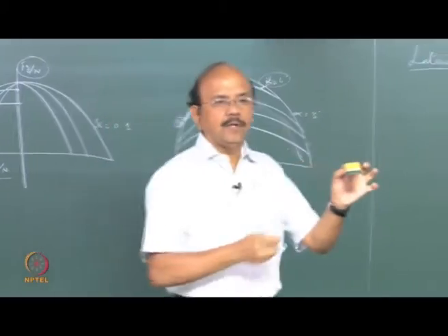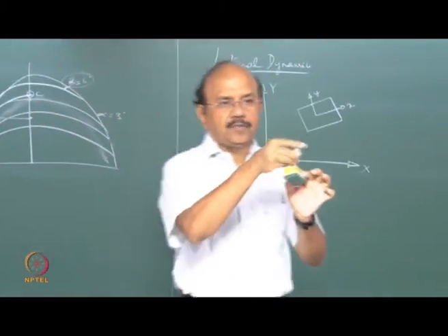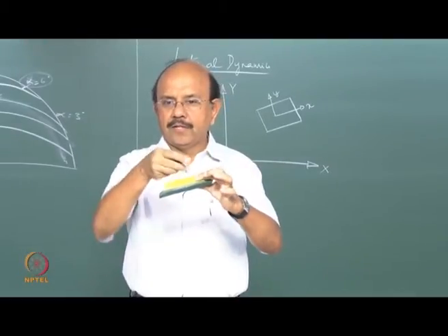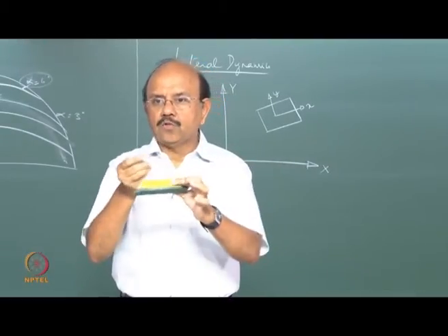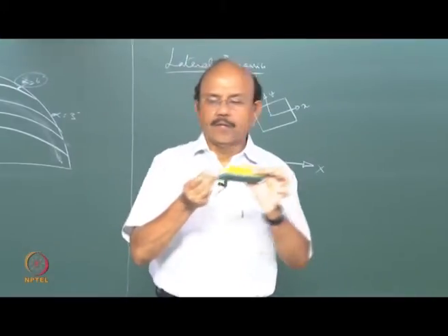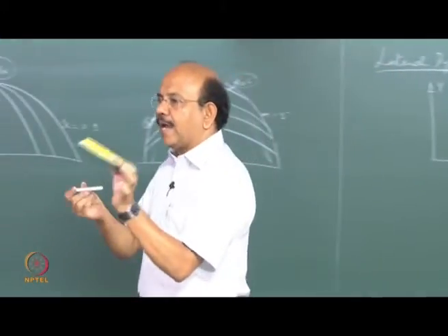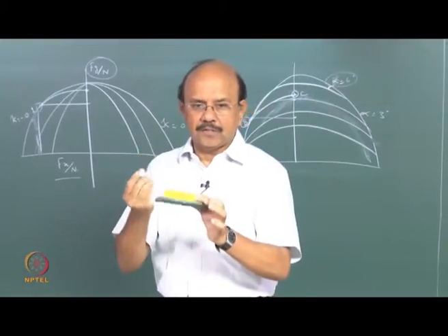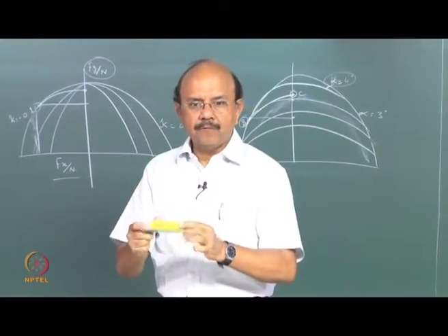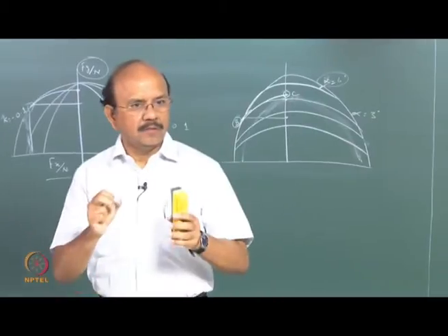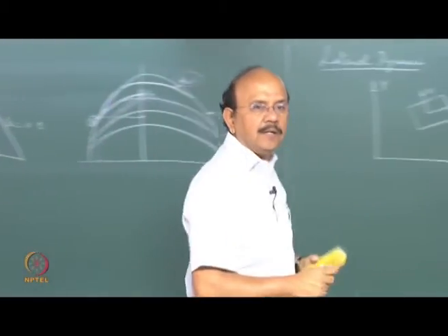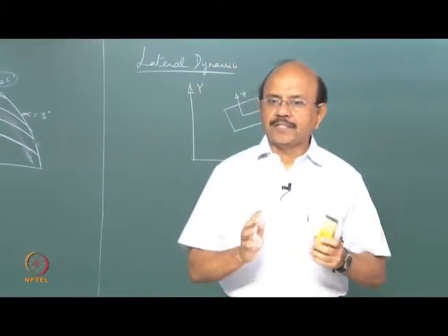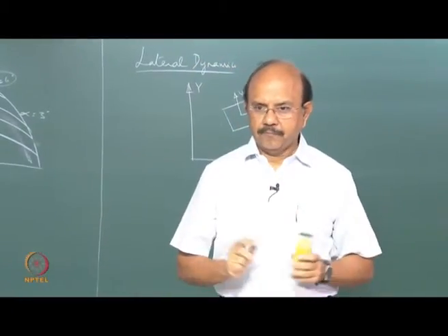Suppose this is the vehicle. So I have a body-centered coordinate in this vehicle. So the vehicle takes a turn, the body-centered coordinate also takes a turn. Okay? So they also move along with the vehicle. In other words, I have to take into account this motion of the vehicle and the body-centered coordinates, right? How do we take this into account? First thing is, that's what we are going to see, and then we are going to apply Newton-Euler equation in order to understand the motion, right?